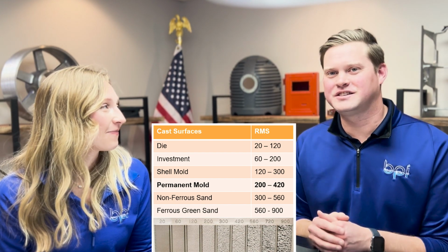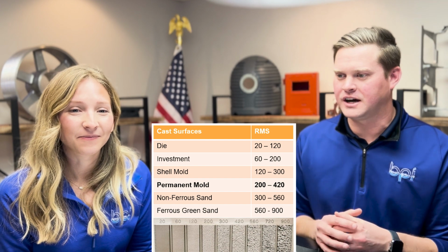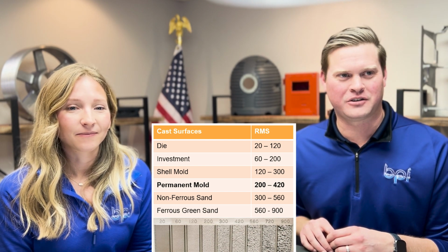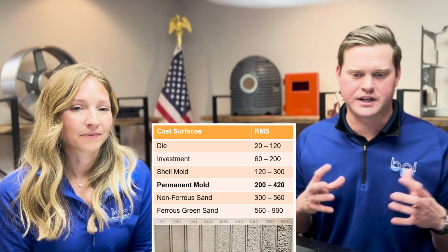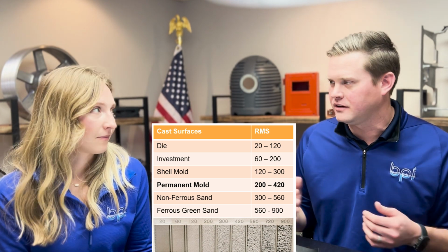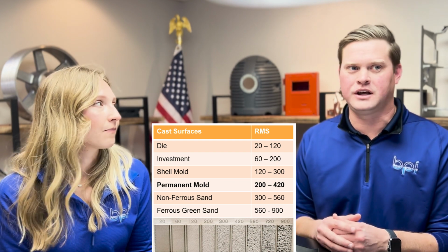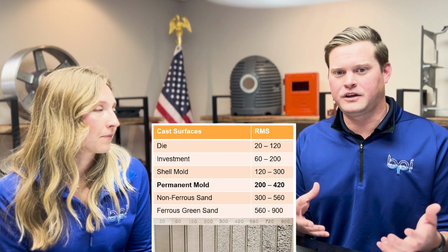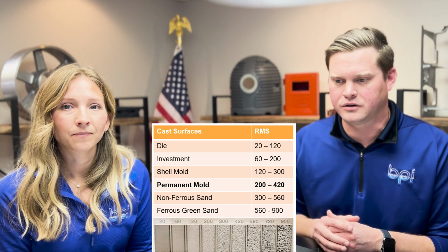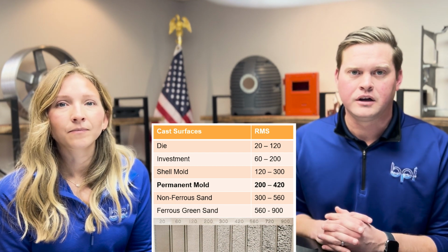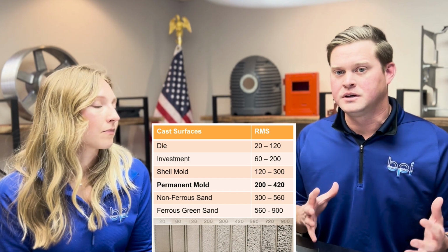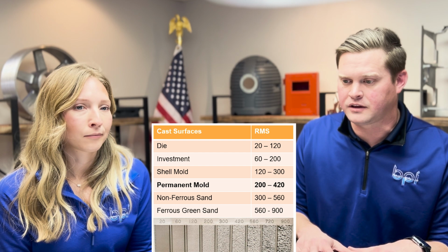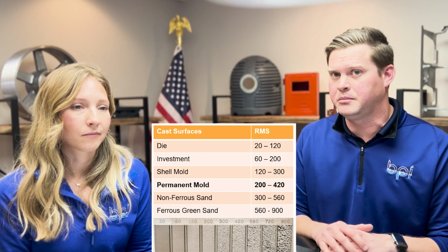Yeah, no, I think the nice thing too is this gives you a range. Again, end goal in mind, as Rachel mentioned earlier, but if you are designing a part that's hidden, do you need 60? If you are designing a part that goes on a medical application, is 200 enough? That's where I think the benefit of reaching out to your preferred supplier and really understanding capabilities comes in, because what we do at our end is try to get the best surface finish coming out of the casting itself, which can actually be better than 200.